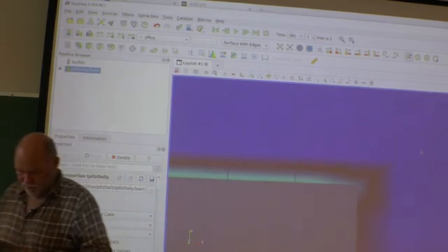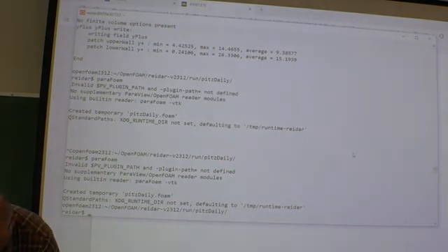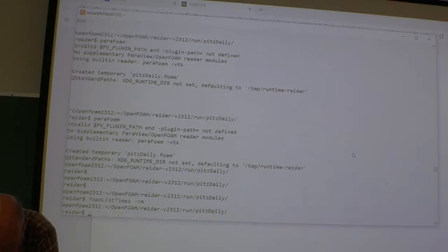That would be better. How can we simply and easily refine the mesh here? Well, let's try it. First, let's get rid of the old result. Where are we here? That one. Remove the result folder, rm -r.